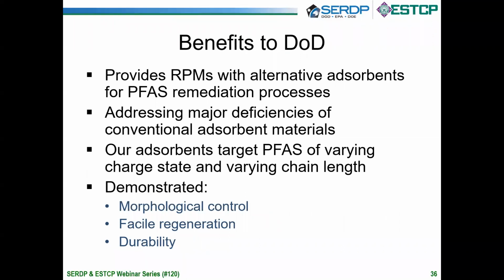This project offers a number of benefits to the Department of Defense. Primarily, we hope to provide RPMs with alternative adsorbents for PFAS remediation processes. And we hope that the alternative adsorbents address some of the major deficiencies of conventional adsorbent materials. We are focusing on not only the widely studied anionic perfluoroalkyl acids, but also PFAS of varying charge state that are known to co-occur with perfluoroalkyl acids in contaminated groundwater. And to date, we have demonstrated morphological control, facile regeneration, and durability of our most promising polymer adsorbents.